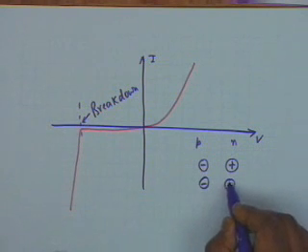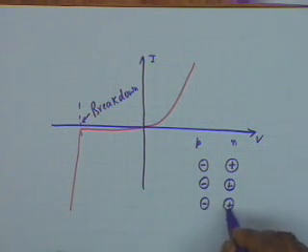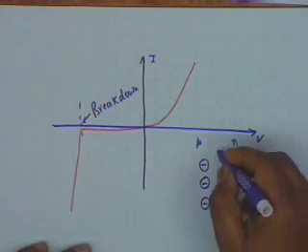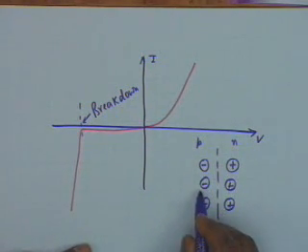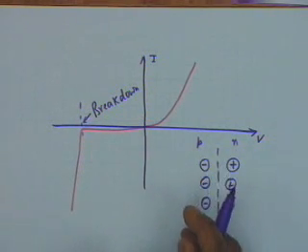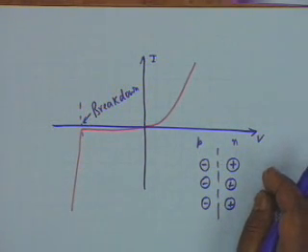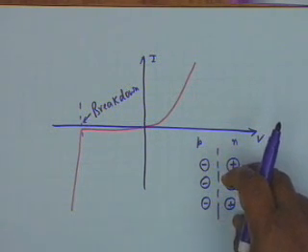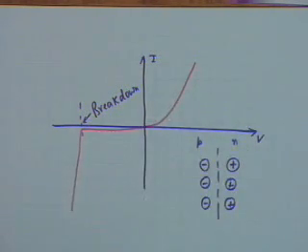These are uncovered charges, that is, the mobile electrons and holes have crossed the junction. The mobile holes from the P type near the junction have crossed to the N region. The mobile electrons near the junction in the N type region have crossed to the left hand side.